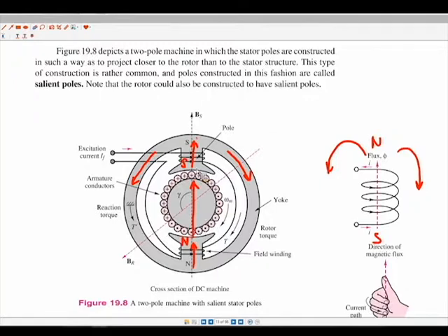So my main message here: what side we call north, what side we call south, really not that important. The most important thing is to know what direction the flux is running in your system. All right. Any questions on that idea? The labels are confusing, I agree. There's not really a good system for it, but what we care about more is what direction the torque is in.